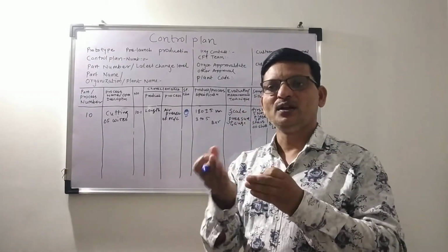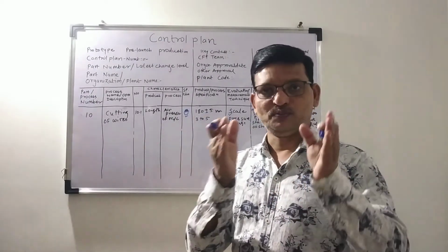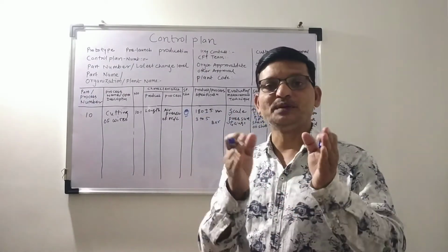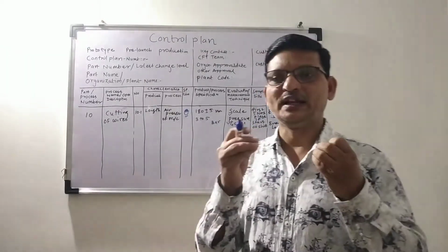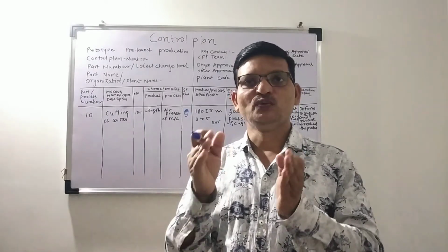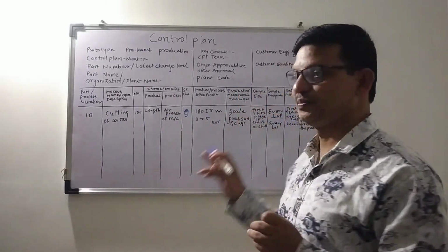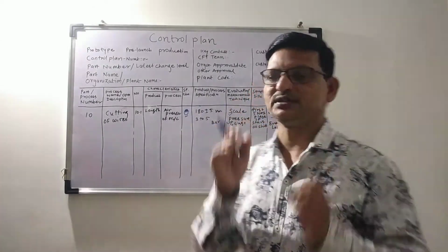And we keep that part until the process ends, until the shift ends. Due to this, if any variance is found in between the process, we will check the first piece and last piece of that process, so we can control that process.